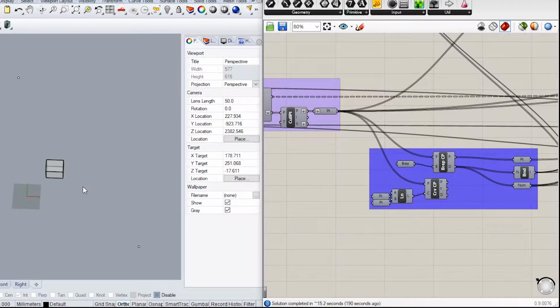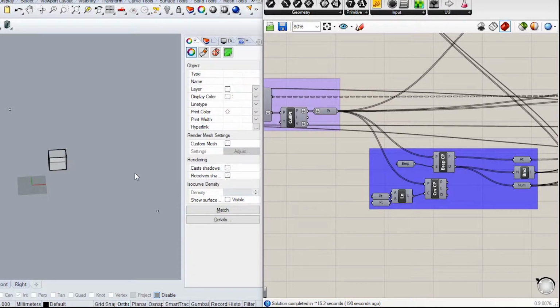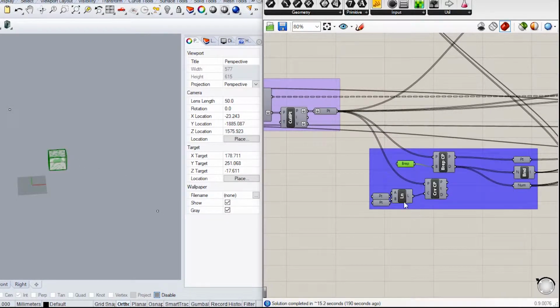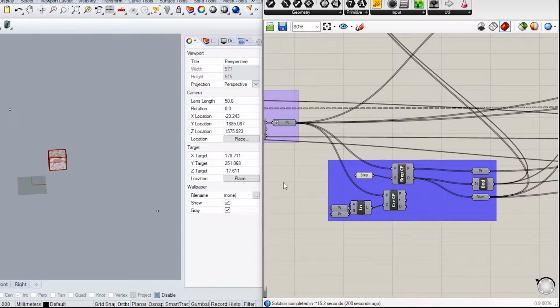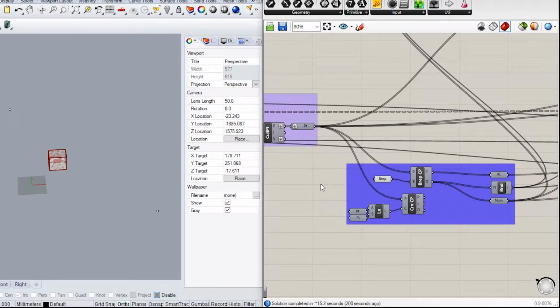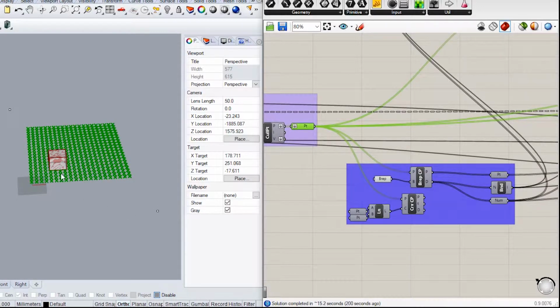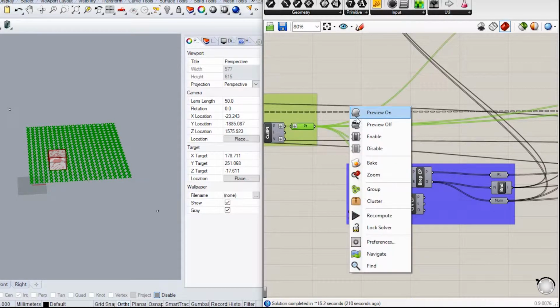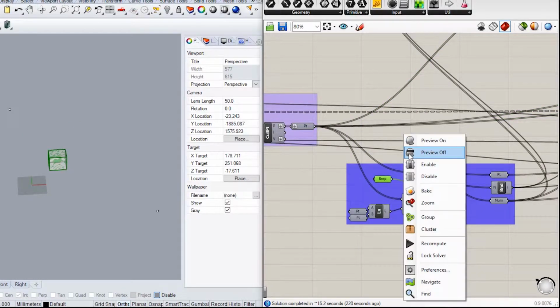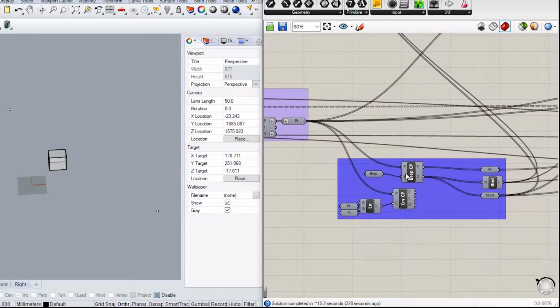First, we will create our attractor, which is a box in Rhino, and we will reference it in Grasshopper. We will want to find the closest points to our box to define the direction at which our vectors will be pointing. And we want to find the distances to use in the magnitude of movement, factor scaling, and degree of rotation. So in order to do that, we will add Brep closest point component, connect the Brep to its Brep input, and the grid points to its points input.